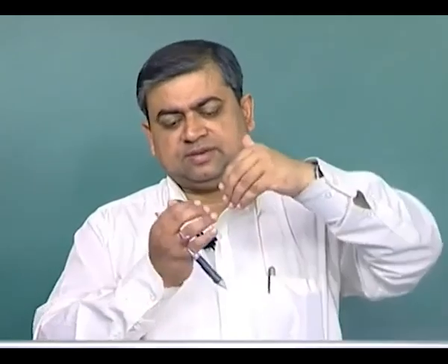So, if there is a difference because of a rapidly approaching tool, in this rate of dissolution, then there would be a tendency of the two surfaces to touch each other. And when it comes to just about touching, there is this sparking phenomenon, which is essentially an ionic discharge, which would happen because of the very small hills and valleys produced on both surfaces, the tool and the workpiece, getting in very close proximity to each other.